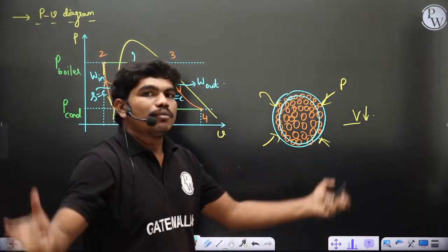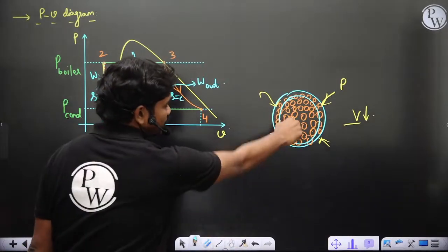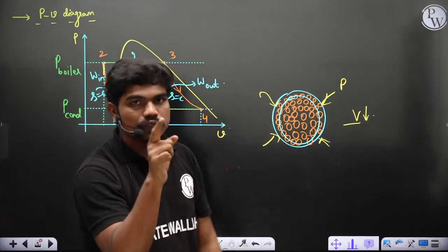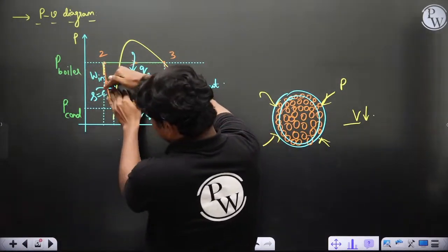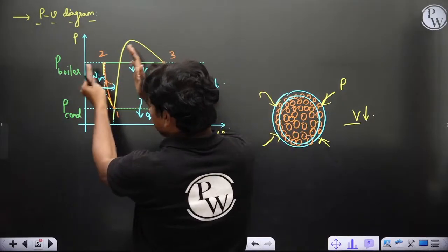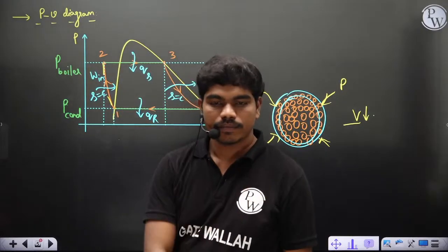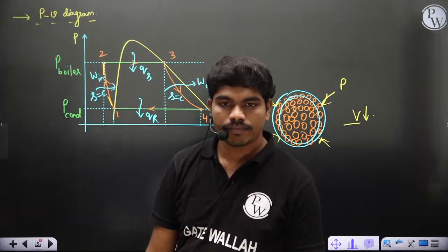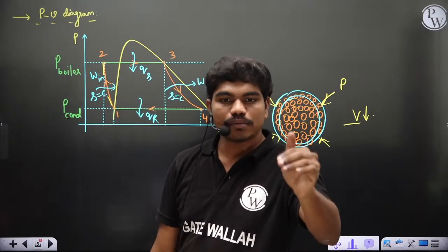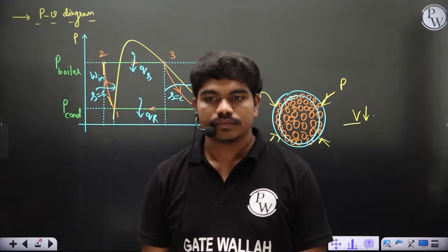After that, even if you apply a further increase in pressure, there won't be enough space, so the molecules cannot go much closer. So almost after reaching this point, even though you are increasing pressure, there is no provision for the molecules to actually come close. So volume almost remains constant in this part. Clear? Because every substance has a certain bulk modulus which changes with pressure and volume. Clear? That's why.